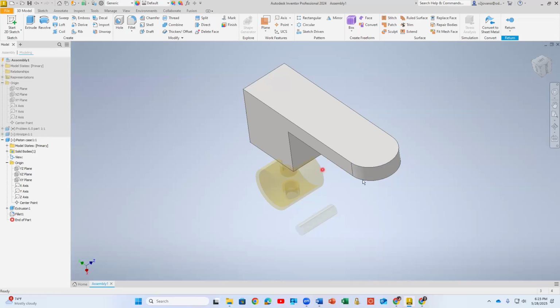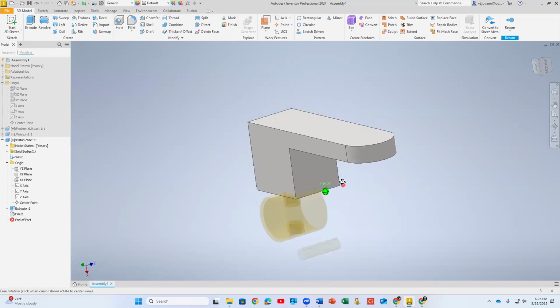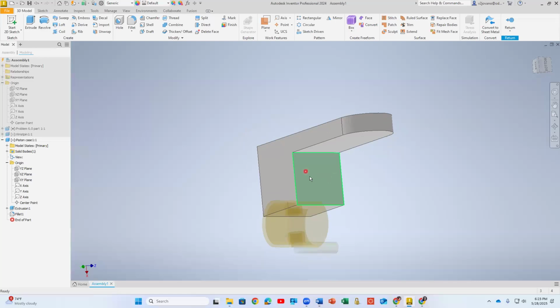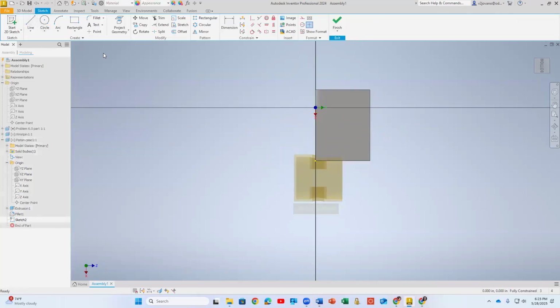So then they want us to draw something. I'm using shift middle mouse click to go to this plane. So I will say, okay, we can right click here, I click on that and I say start 2D sketch there. And all we have is one circle somewhere inside, and I can dimension the first dimension, like the location of the center.